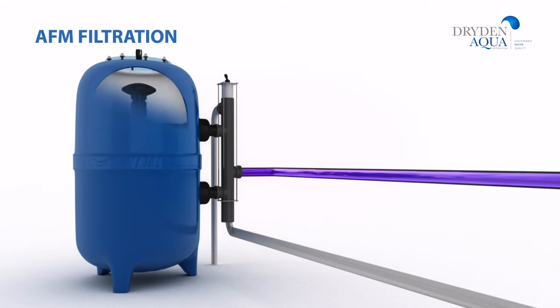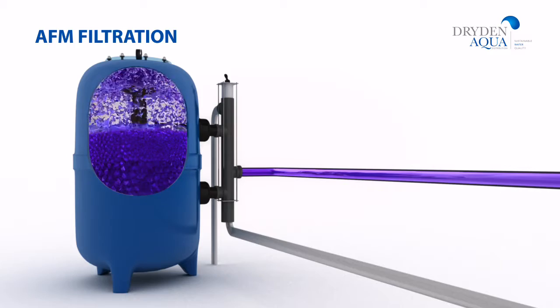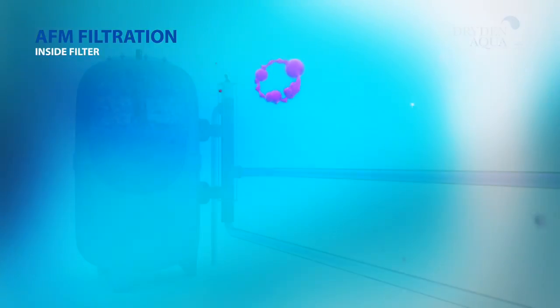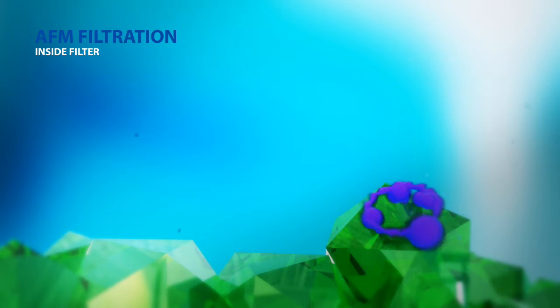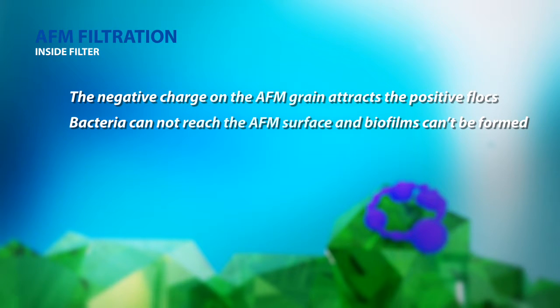AFM has a surface area 300 times greater than sand and a negative surface charge which attracts all particles that have been given a positive charge by APF. The strong negative zeta potential prevents bacteria forming biofilms on the surface of AFM. By eliminating the acidic biofilm, trichloramine will not be formed. Trichloramine, also known as nitrogen trichloride gas, is responsible for the chlorine smell in pools. The toxic gas also causes eye and lung irritation. AFM helps to solve this problem.